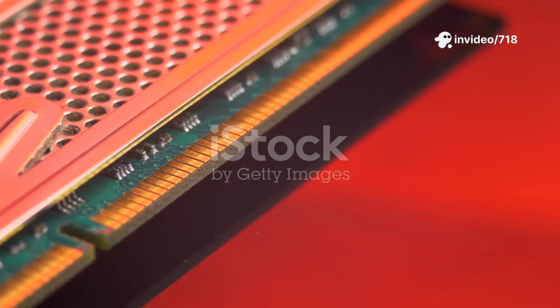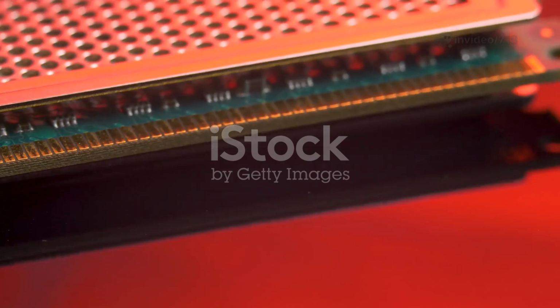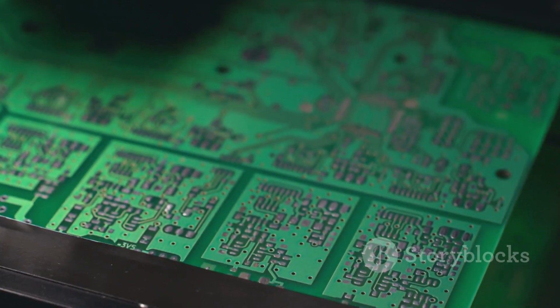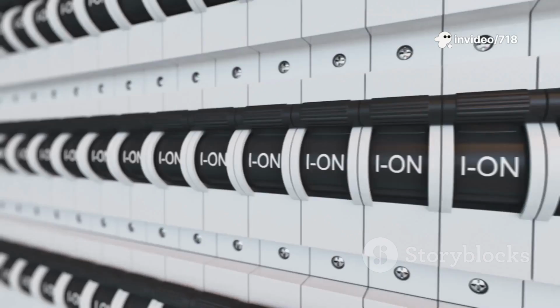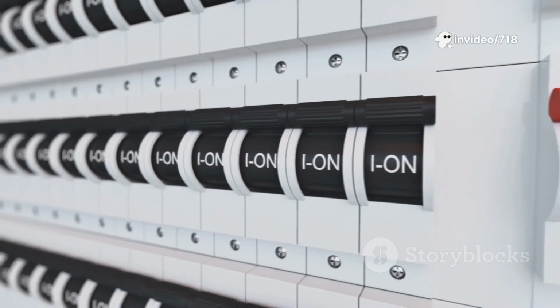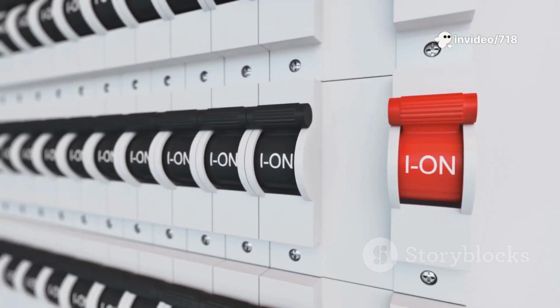Instead of a simple one transistor, one capacitor cell, an SRAM cell is typically built from a cluster of 6 transistors. This design acts like a flip-flop circuit, actively holding the data in a stable state. It's like having a light switch that stays in the on or off position you set it to, rather than a leaky bucket you have to keep refilling.